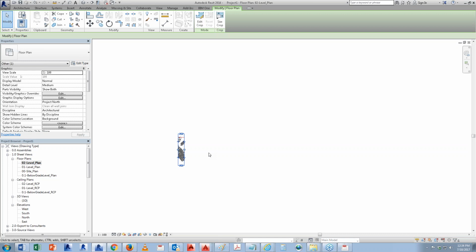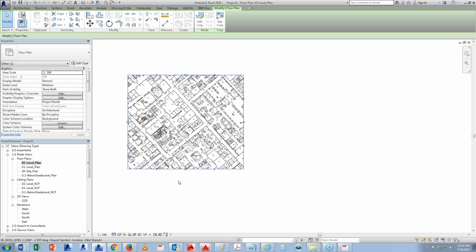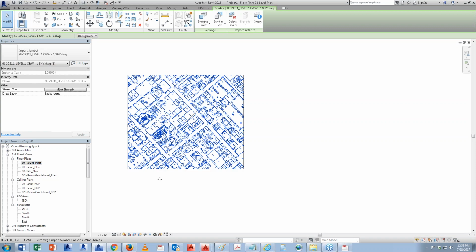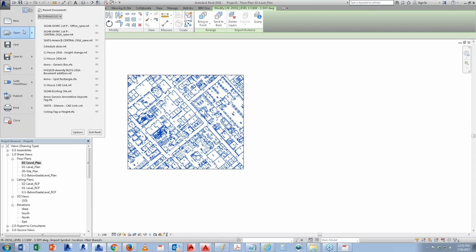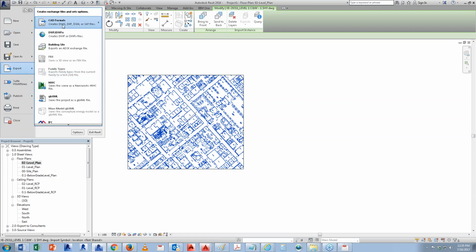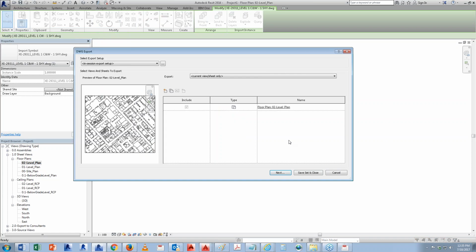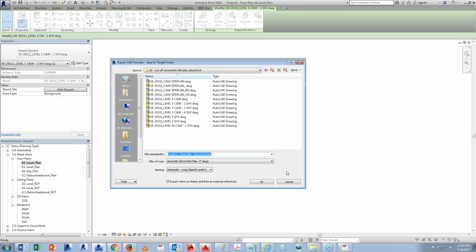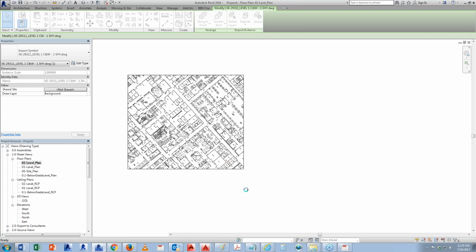The problem with AutoCAD X-clip is that the rest is still there, and it increases the file size when you extract multiple drawings, bogging it down. Yes, it will slow you down. So this in Revit is essentially like an X-clip, except it's really a crop. It's gone. Yes. Okay, let's say you want this, and now I'm going to export this out. Export drawing. Let's say that's my view. I'm going to put it in there and say okay.